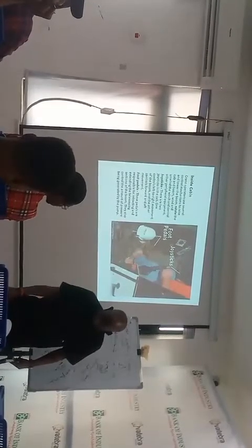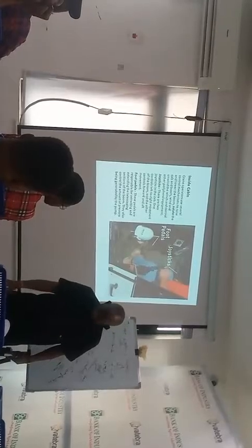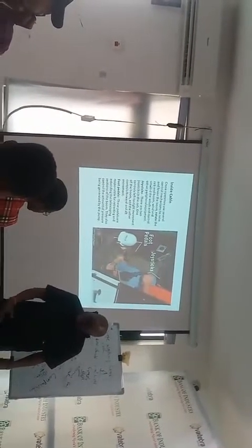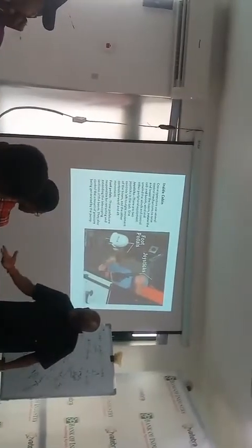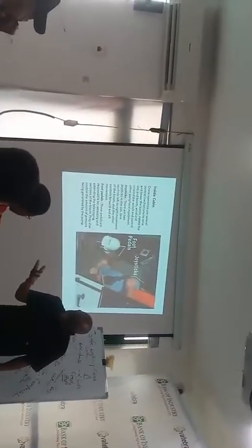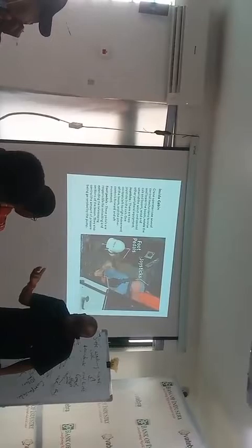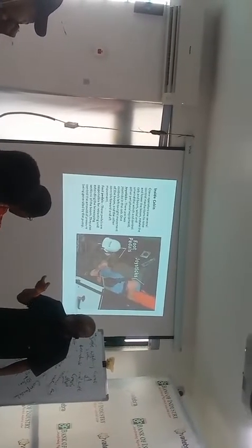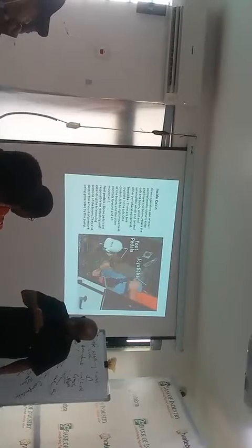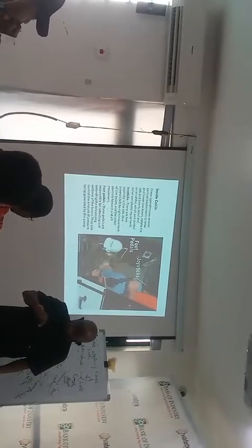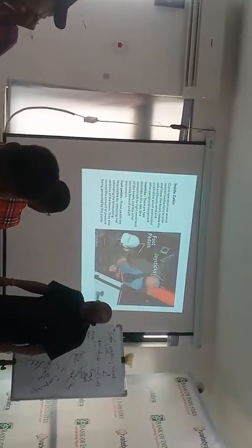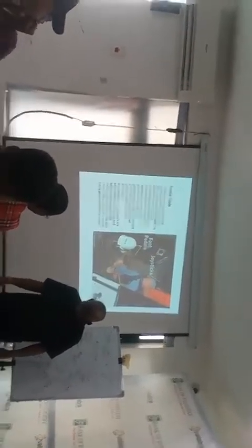Then you do what we call daily pre-checks. You check the engine before you start. You check the water. You are not a technician, but you must check all those things. The technician will not come to check the water level for you or the engine oil level for you. You must do it.